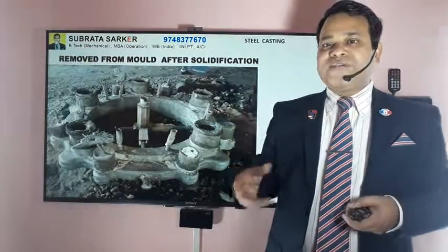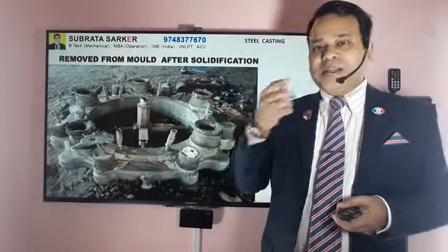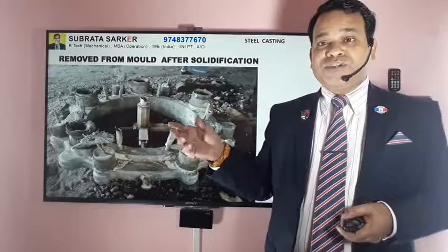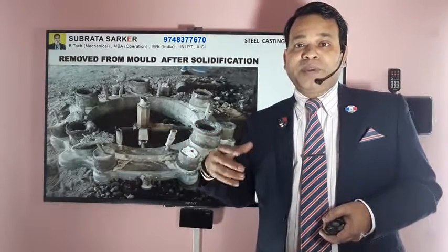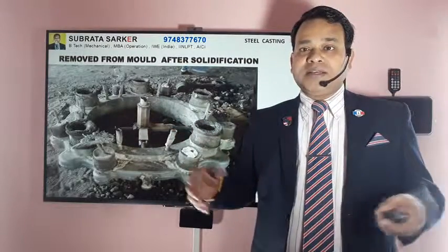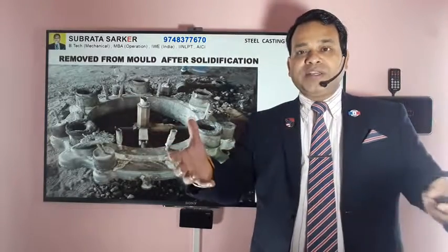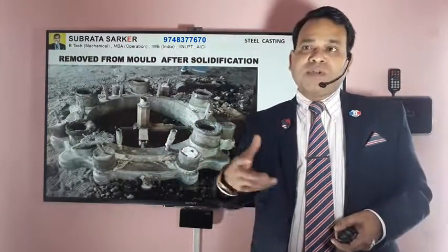And after solidification, this will be the typical shape of a component, where a lot of things are projected which are not part of the component, but are there to make the process work, like for the pouring. A lot of things are there, technicalities of the casting. So this is how it looks when it comes out of the mold cavity after solidification.